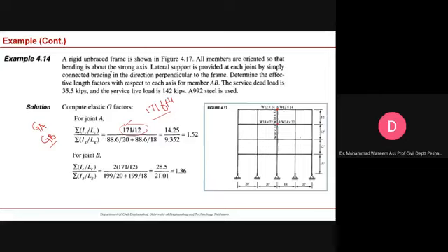Now at this point there are two beams, so the lengths of these beams are different. One is 20, the second is 18. So this is the I value, okay? You can take it from the manual. You compute this GA. Now similarly, you can calculate GB. At GB, you have two columns, and they have the same section. So that's why they have doubled the stiffness value computed for the single column.